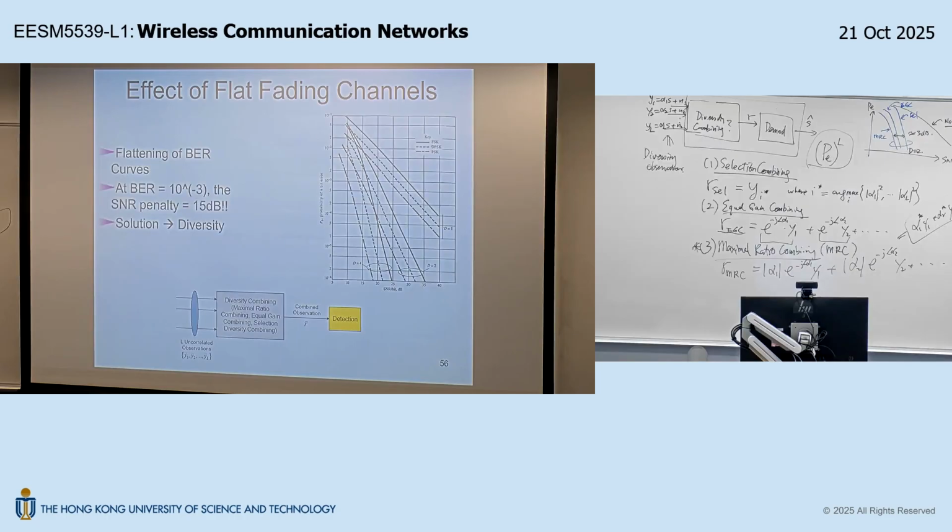Because all the preamble observations are coming from the first receive antenna, it naturally carries alpha 1. Is that okay? And then from T1 to T2, I configure the switch to position 2. In this case, the input to the CE will be coming from receive antenna 2, so it will contain alpha 2, right? Then I will have alpha 2 hat here.